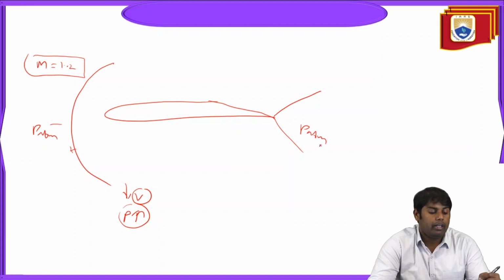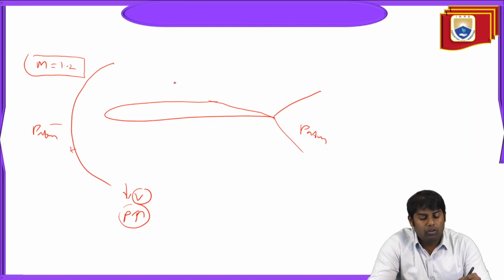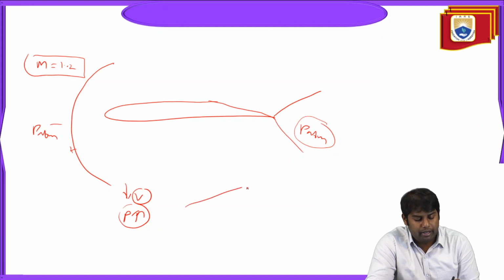Okay, so here the flow gets compressed, pressure increases, and then again at this region the flow expands. An expansion wave forms such that pressure decreases and matches the atmospheric pressure. So that's why we cannot use the airfoil shape geometry for the high subsonic regions, or let's say the supersonic regions. So that's why people have invented, or started using, delta wings.